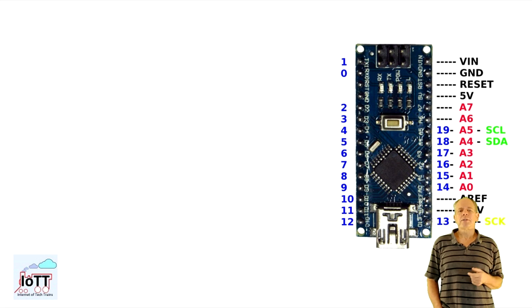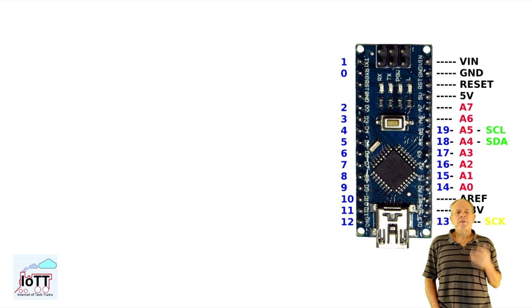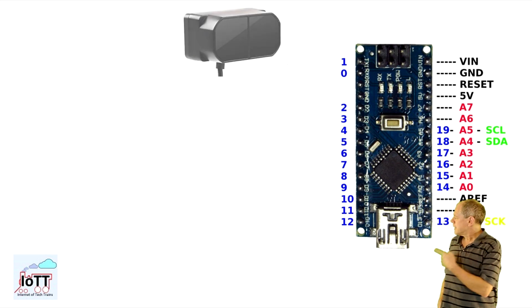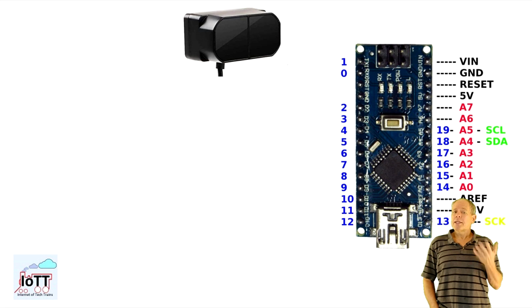Here are the components I plan to use. An Arduino Nano board. The Nano board is more or less identical with the Arduino Uno, but has a much smaller footprint, that's why I prefer it. The TF Mini Plus sensor. This is a LiDAR sensor with a measuring distance of up to 10 meters according to the datasheet. More important, the opening angle of the laser beam is small, so it should be possible to detect a locomotive, I would hope, when it is about 10 feet away.